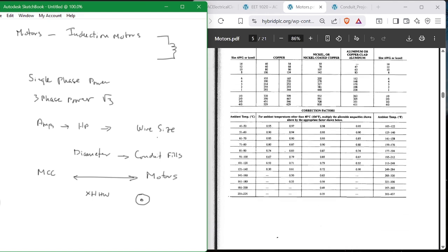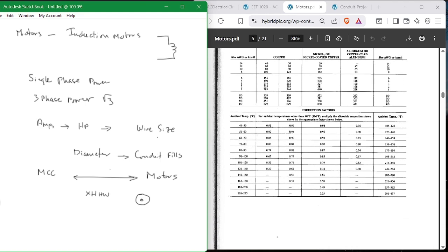But you can decide and then sort this all out and put this all together. And congratulations, at the end of that time, you will have built a wiring diagram, or some people call it a riser diagram. So it's a wiring fill diagram. If you show a picture of the different conduits with the different fills and the different sizes, and all of a sudden you start using Excel spreadsheets because they're the best way to add all these up and get them all finished off. So that's that.